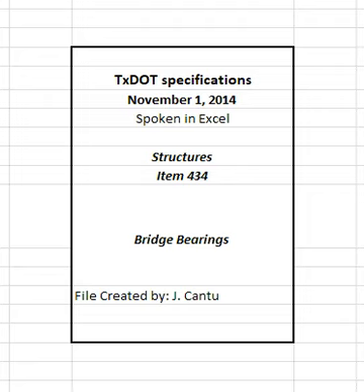2.2.3 Special components. Provide steel guide bars and bottom plates, when required for sliding elastomeric bearings, in accordance with the plans. 2.2.4 Coatings. Provide coating materials as required in accordance with item 445, galvanizing, and DMS 8104, paint, shop application for structural steel, unless indicated otherwise on the plans. 2.3 HLMR bearings.